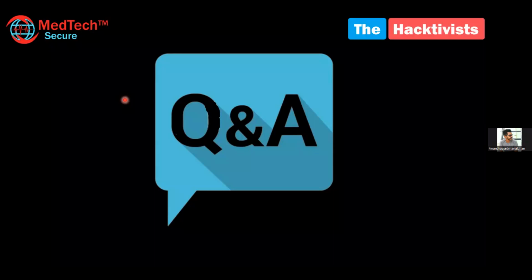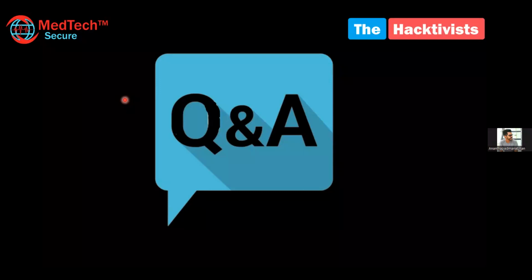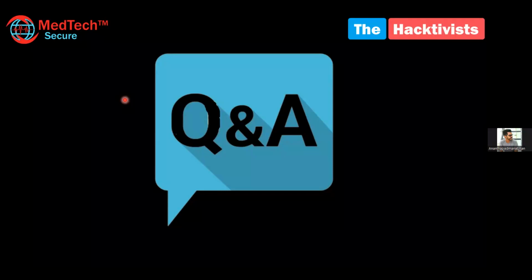So first, if we understand the microcontroller being used, then our task is to find out the protocols it uses. In your case, since it is using I2C, you can go ahead with the logic analyzer. In today's session we didn't discuss much regarding that because of the time constraint, so we only focused on the UART part. Depending on the protocol, there are different security test strategies to be followed.